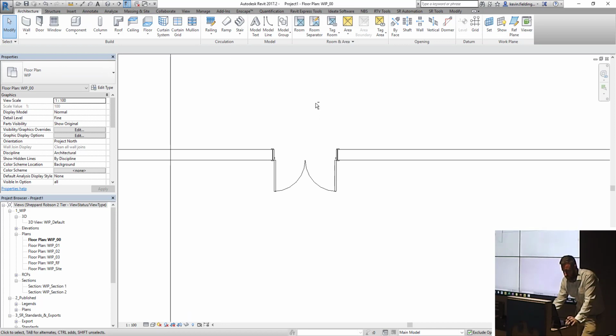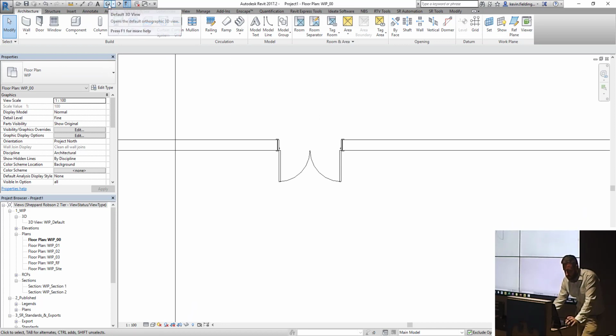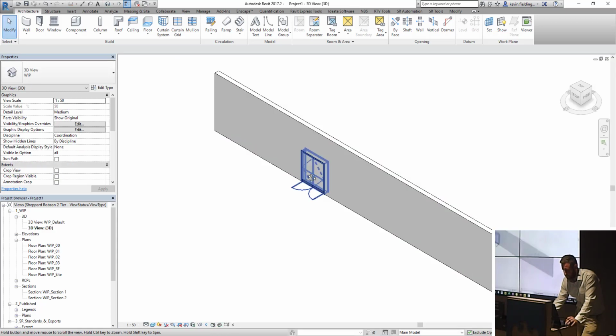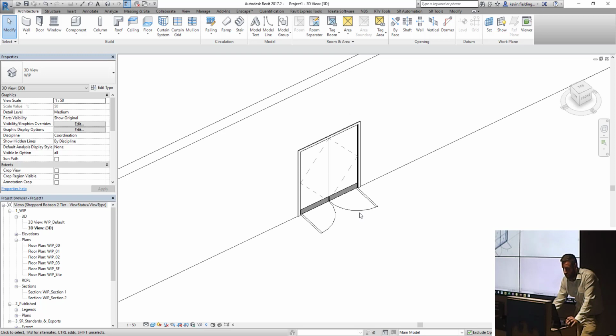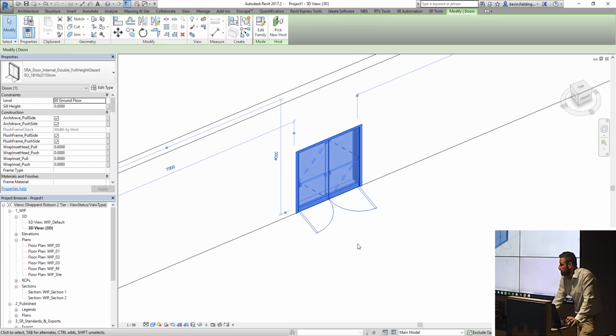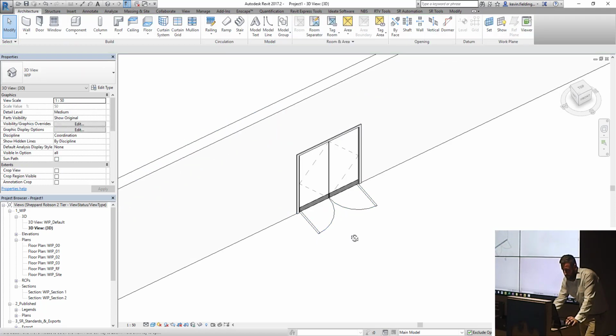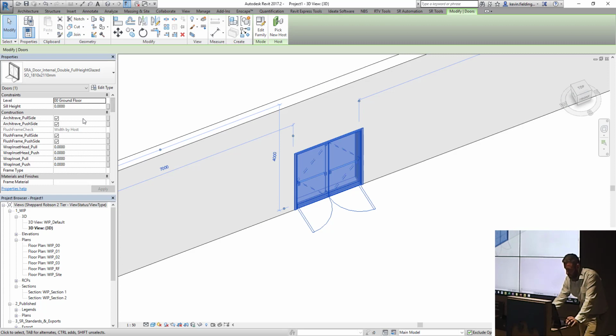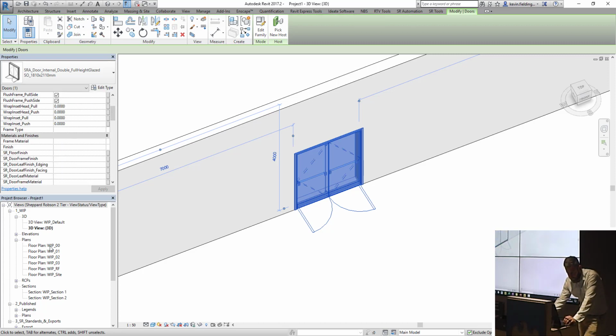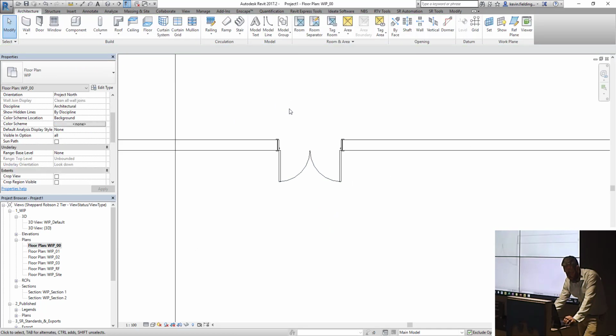And a tip as well is build them in the earliest version that your projects are working in. All our libraries are currently built in 2017. That way you don't have to worry about telling people in the office that you can't have the doors because you're not working on that version of Revit. Okay, so I did that video before that showed stuff flexing and bits and pieces, covered all the parameters and whatnot, but let's just go to plan and show it there instead.